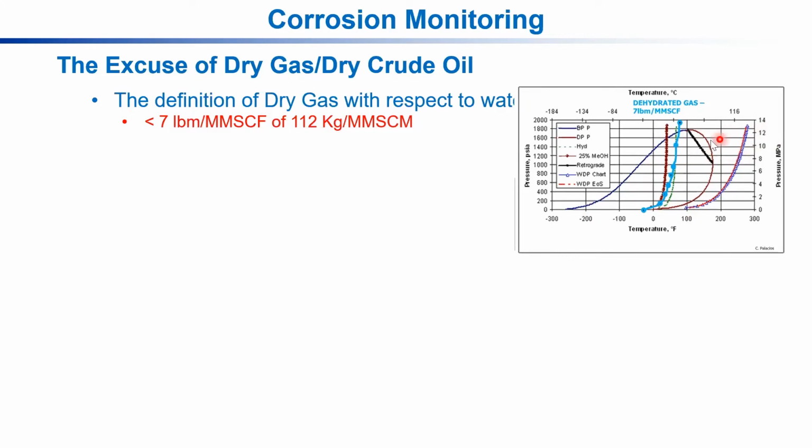So I move this line to this line. Now this is the dehydrated line. Now I am operating in this area and I should not have water. See what I'm saying? I should not have water, because I dehydrated the gas.